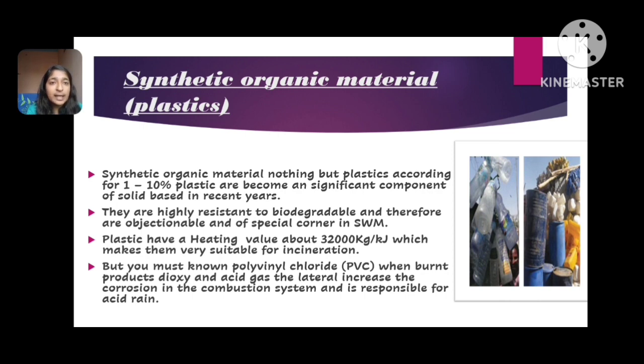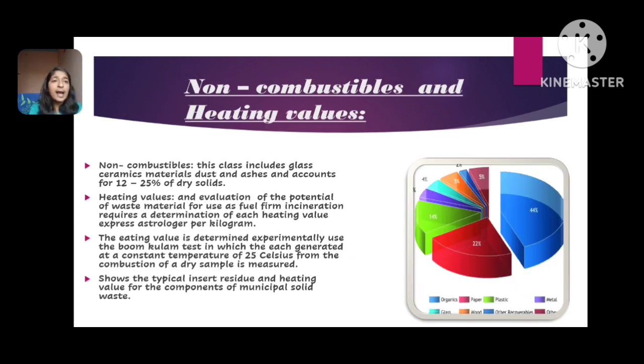Synthetic organic material. Synthetic organic materials are nothing but plastics. Accounting for 1 to 10%, plastics have become a significant component of solid waste in recent years. They are highly resistant to biodegradation and deserve a special corner in solid waste management. Plastics have a heating value of about 32,000 kilojoules per kg, which makes them very suitable for incineration, and PVC burns to produce hydrochloric acid gas that increases corrosion in the combustion system and is responsible for acid rain. Non-combustibles and the heating value.